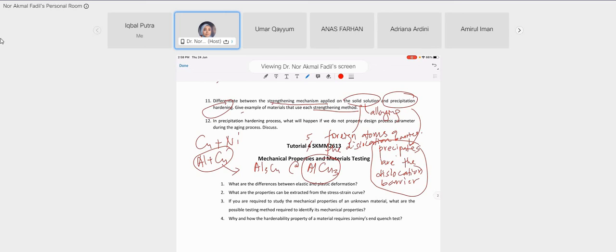this material is able to produce intermetallics, which is aluminium 3 copper or aluminium copper 3. This is an intermetallic precipitate. By a proper heat treatment process, you can produce this precipitate. Okay, you can just Google precipitation hardening example metal. So not all alloy systems can produce this. Even though you have this alloy, only a specific range of composition will produce precipitate. Not all compositions. Okay, so whatever composition can produce this precipitate can be a material that has gone through precipitation hardening.